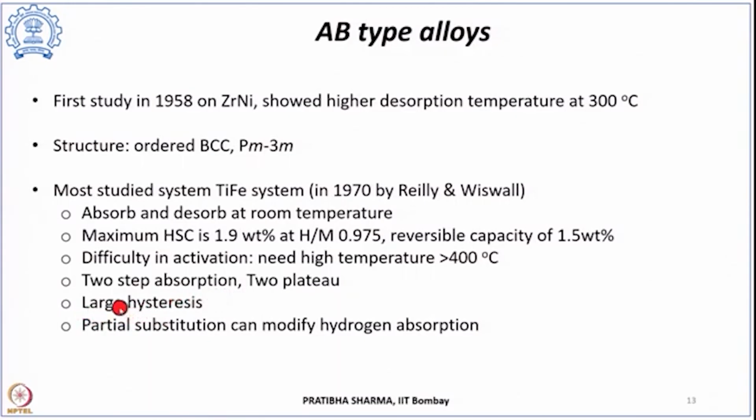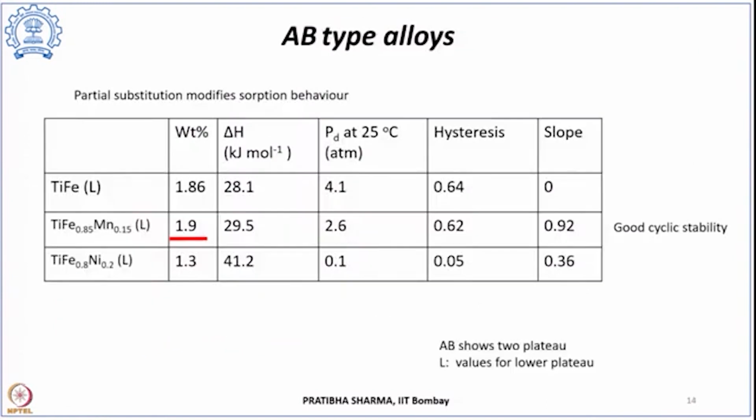and there is large hysteresis in these types of systems. However, we can address these problems by partial substitution, and if we do a partial substitution, then that will change the hydrogen absorption characteristics.